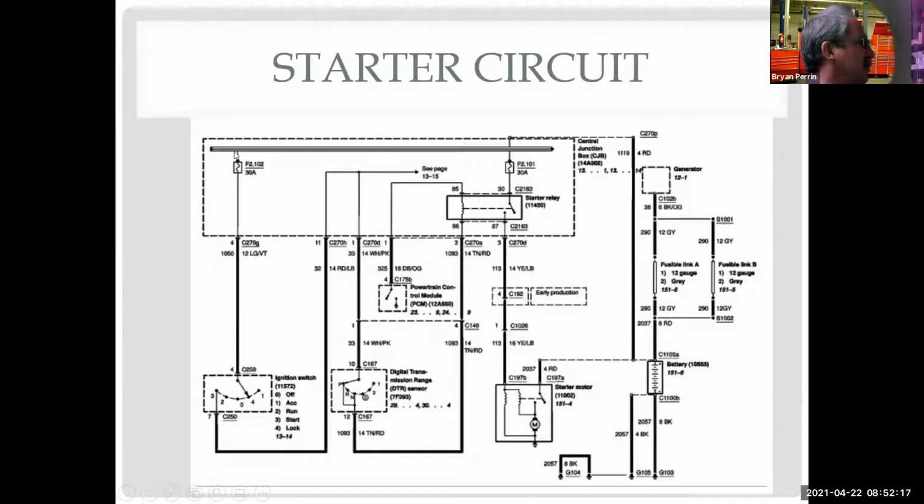So in order to start this vehicle, I have to have power come up, good fuses. Power comes down through here. Make sure I'm in park or neutral. Up to this relay, and then the computer decides if I can start the car.